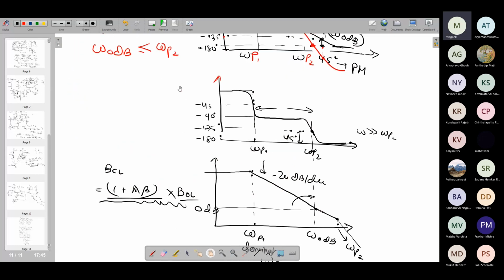Another thing that you should also look at is gain margin. So I have given you the definition of phase margin. Theoretically, if you read textbooks, you will find statements like two pole systems are unconditionally stable. So if you have exactly two poles in the system, the feedback system will be unconditionally stable. That means you are making a feedback system with a feed forward path, and then you are putting some beta feedback, and then you are subtracting whatever negative feedback.